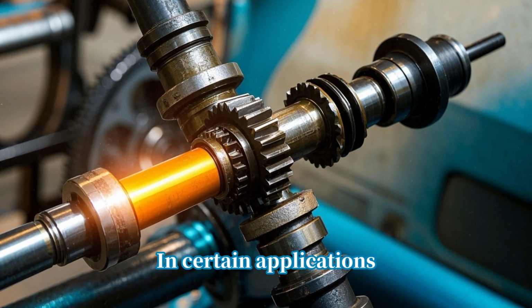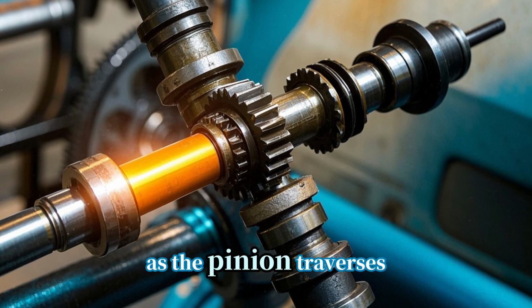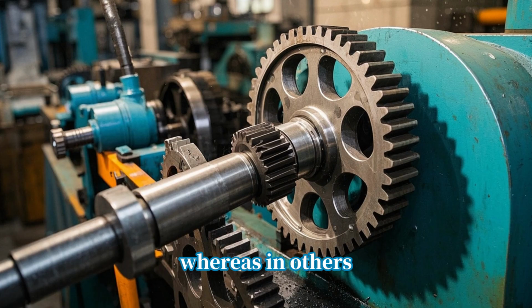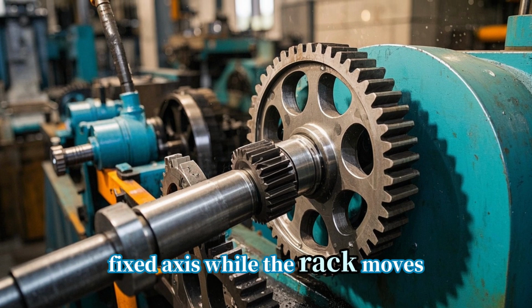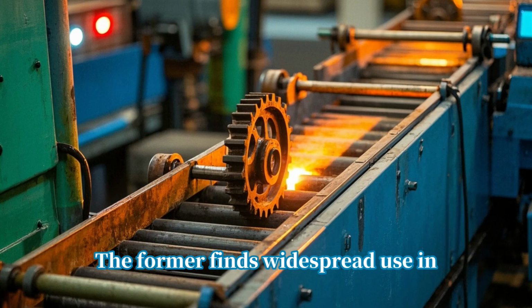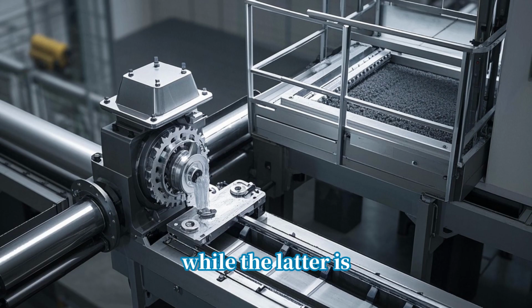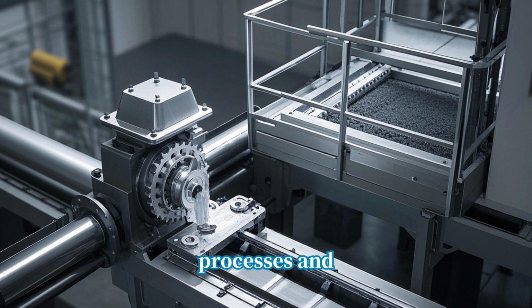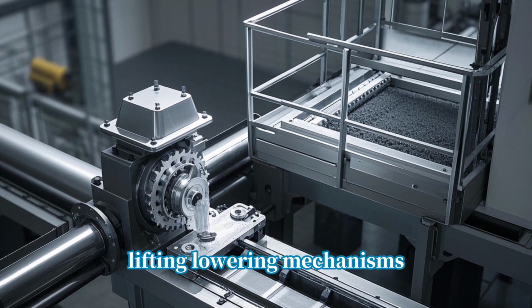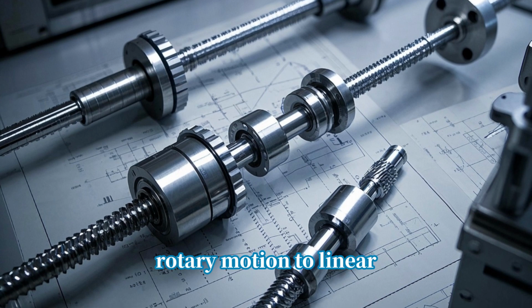In certain applications, the gear rack remains stationary as the pinion traverses, whereas in others, the pinion rotates about a fixed axis while the rack moves. The former finds widespread use in conveying systems, while the latter is applicable in extrusion processes and lifting-lowering mechanisms as components for converting rotary motion to linear.